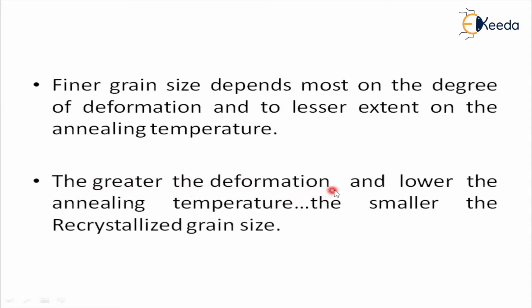The greater the deformation and the lower the annealing temperature, that means if the deformation is more, automatically the annealing temperature will be very, very low, the smaller the recrystallized grain size. So size here plays a vital role in changing the material properties.